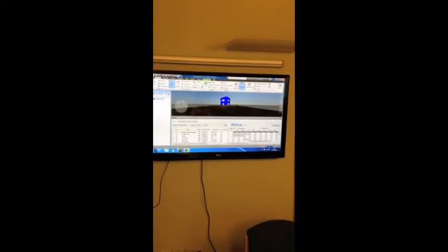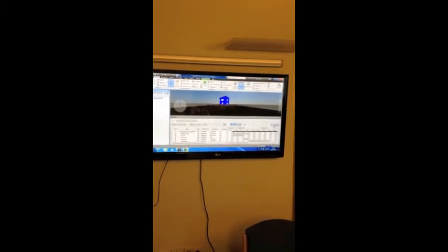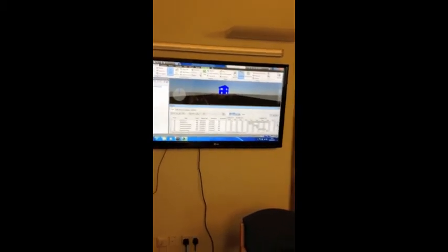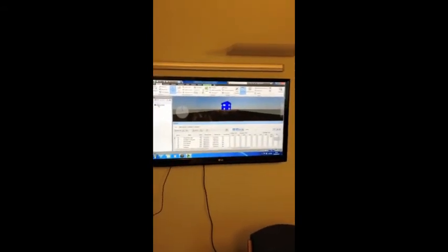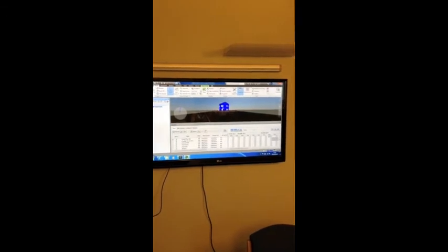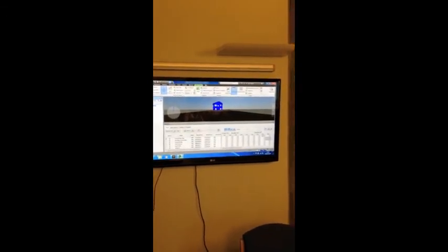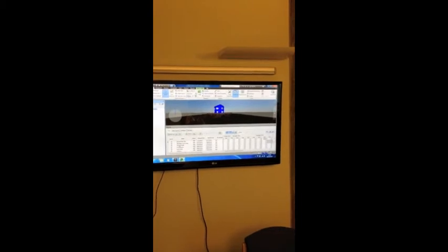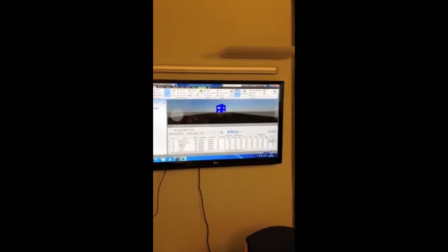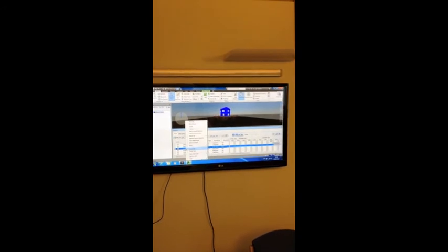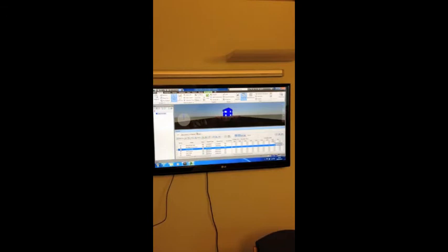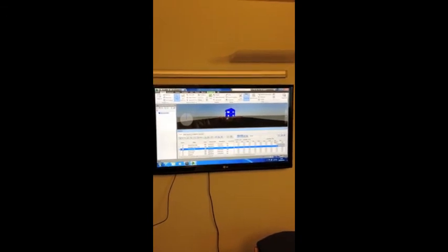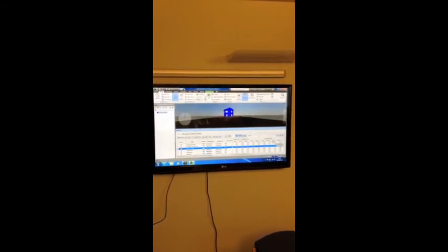Now you need to connect the objects in the model with the relevant item in the programme. So if we scroll down at the bottom to External Walls, you click on the selection set that you've just created, and that highlights all the external walls in the building. You then hover over the External Walls task in your programme, and you right click and scroll up to Attach Current Selection. And that has attached the external walls to that item in the programme.